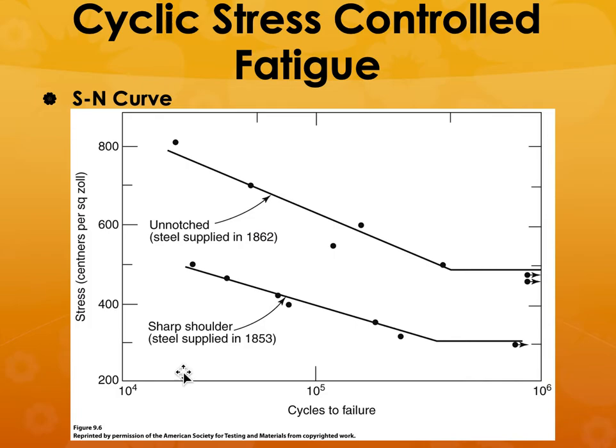But suppose you reduce the stress to, no, I'm sorry. If you reduce the stress to say 700, then it can last up to 8 into 10 to the power 4. If you reduce it to 400 ksi, then you may not even find any failure at all.